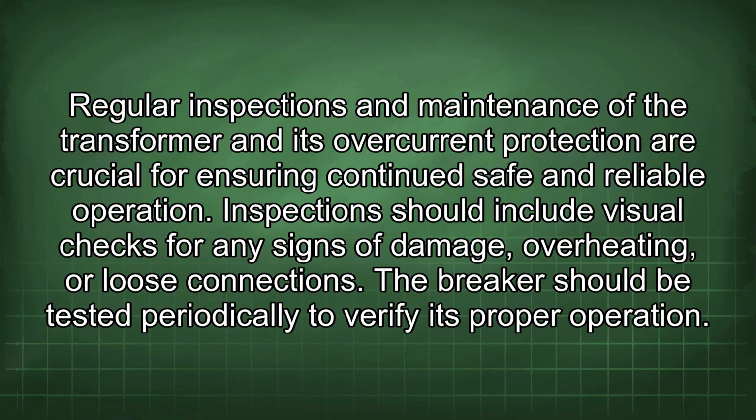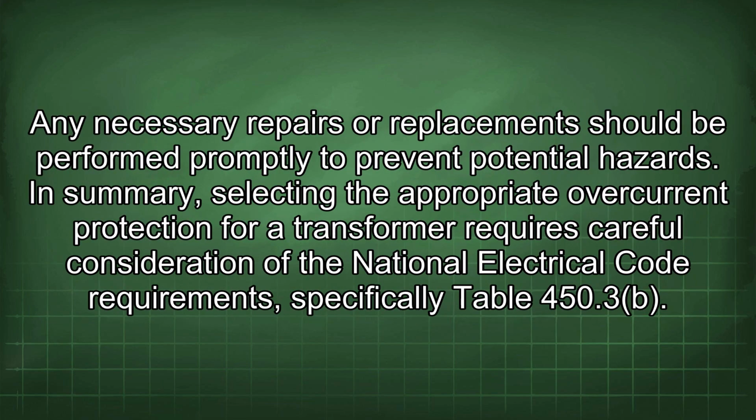Inspections should include visual checks for any signs of damage, overheating, or loose connections. The breaker should be tested periodically to verify its proper operation. Any necessary repairs or replacements should be performed promptly to prevent potential hazards.